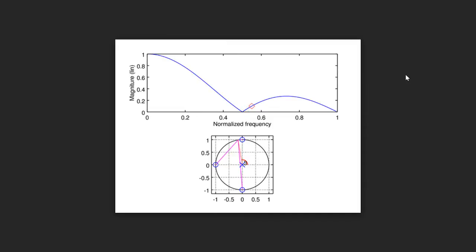So basically, the amplitude response of this FIR system, the 4-point running average, depends only on those distances. And a couple of special points here. We are exactly at the same point where we have a zero, meaning that the amplitude response goes exactly to 0.